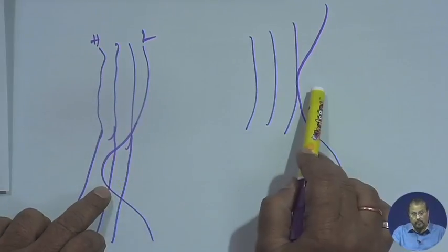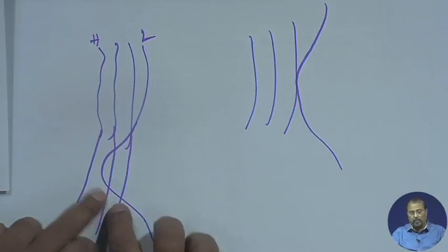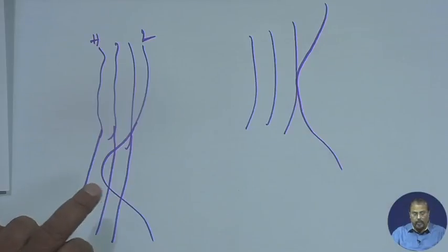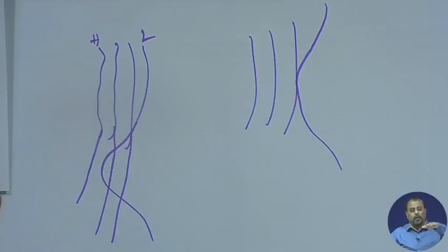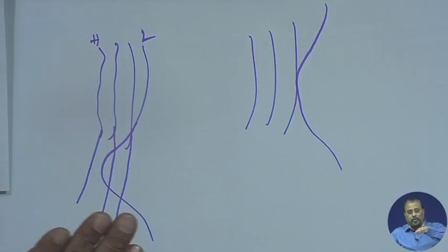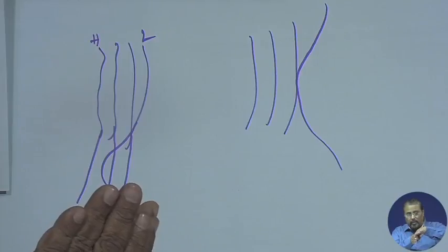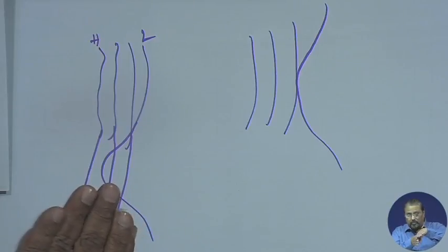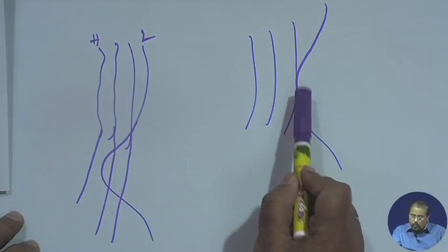But if it happens, first check that it is not a mistake, then there must be some reason for which it has happened. When this happens, when it merges, suppose one contour level and then the next contour, and one contour comes here and then merges with this, that means there is a verticality. So, there is a drop from this particular level to the lower level.